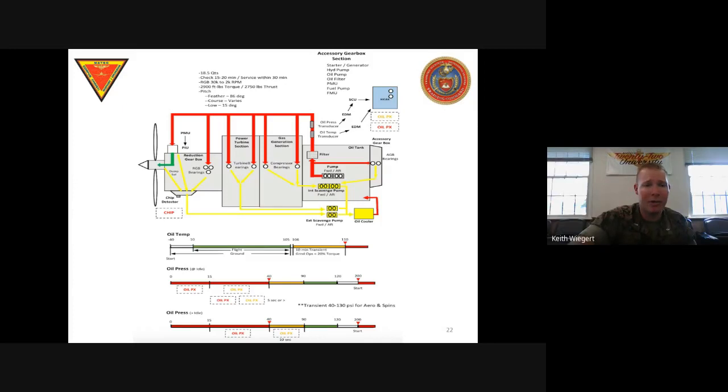Our blades are going to be feathered approximately 86 degrees from the perpendicular plane, and then we're going to put the maximum amount of oil in there and go all the way from feathered through high pitch blades and all the way down to low pitch blades, which is going to be the maximum oil condition, and that's going to rotate our blades to 15 degrees from the perpendicular plane. So those little thin slices, right?